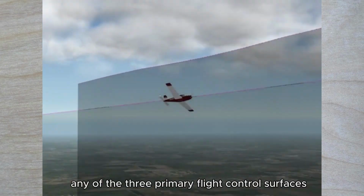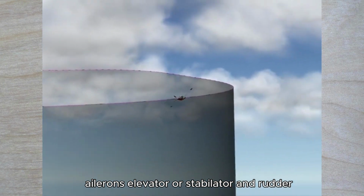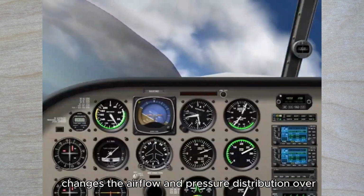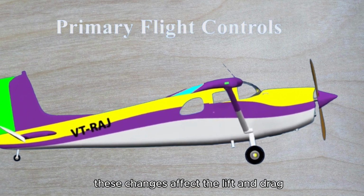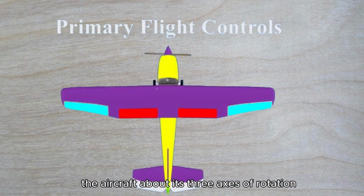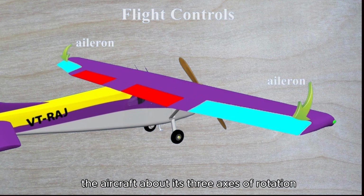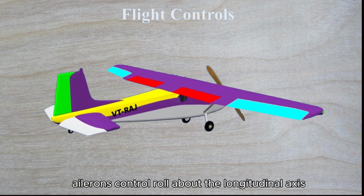Movement of any of the three primary flight control surfaces, ailerons, elevator or stabilator, and rudder, changes the airflow and pressure distribution over and around the airfoil. These changes affect the lift and drag produced by the airfoil or control surface combination, and allow a pilot to control the aircraft about its three axes of rotation. Ailerons. Ailerons control roll about the longitudinal axis.